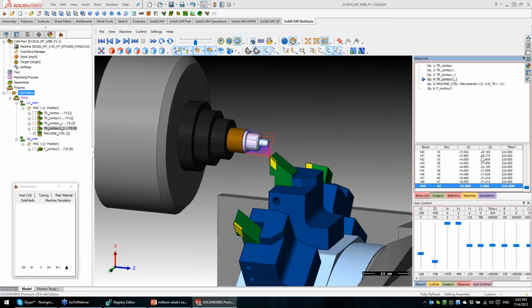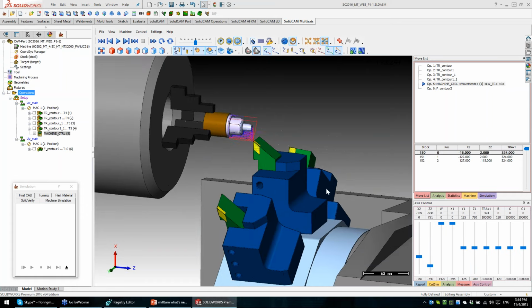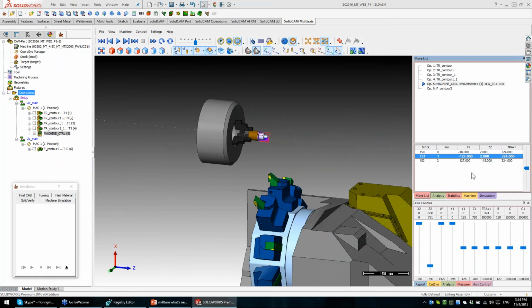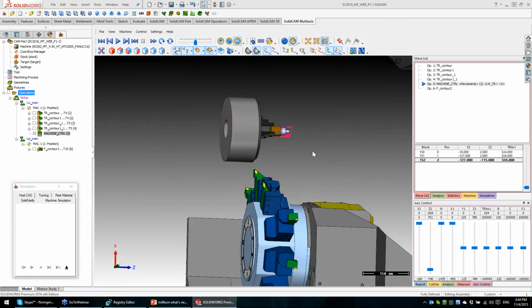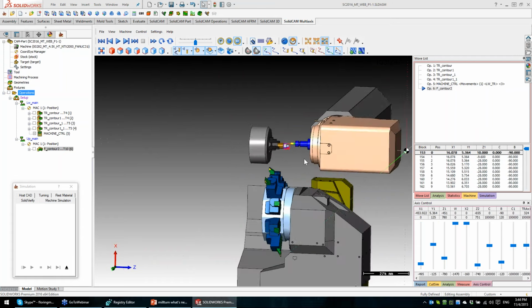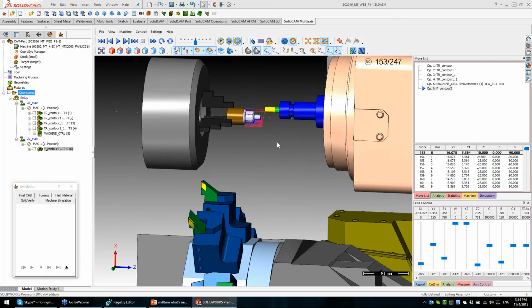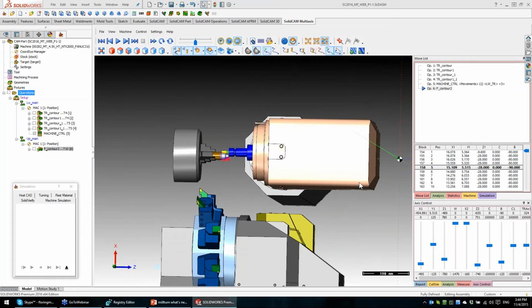Finish the turning, and in the machine control operation, X is going to reference, Z is going to minus 655 in the machine coordinate system. And now the upper turret can start working on the face of this part with no collision.